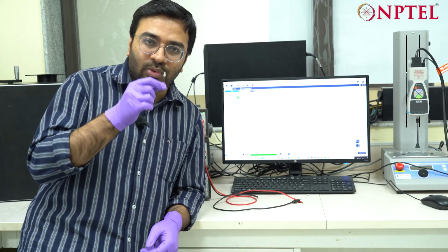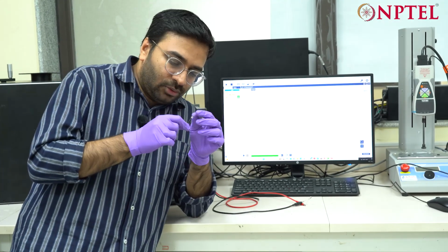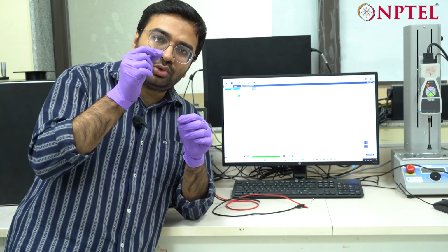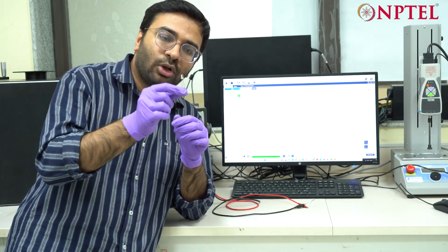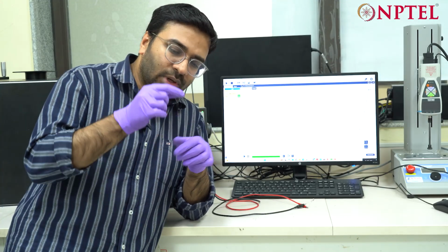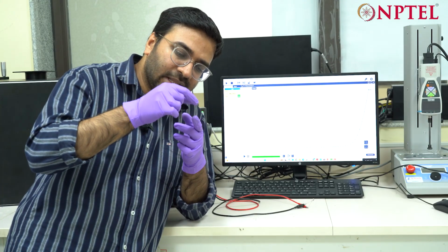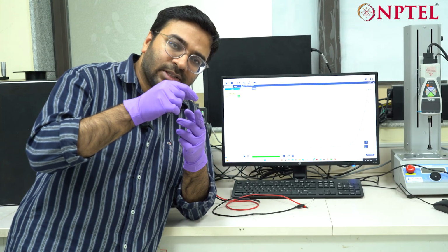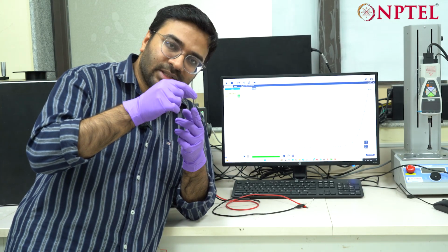So, here we will do an experiment with an LED, which is basically a diode because it is a light emitting diode. So, you should get characteristics which are similar to a diode. But before we do the experiment, let us understand how we can connect the LED so that we can get proper characteristics. If you look at this LED, it has 2 terminals, just like a PN junction diode. And if you look at the length of these terminals, one is a little bigger than the other one. The long terminal is basically positive, the short terminal is negative.